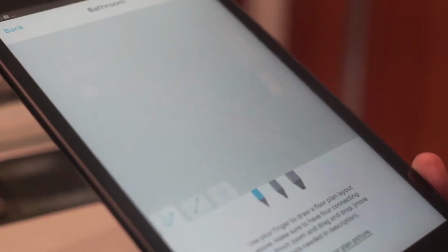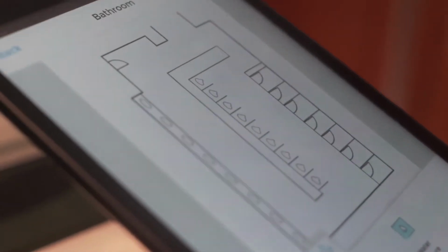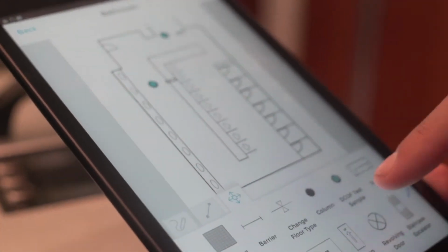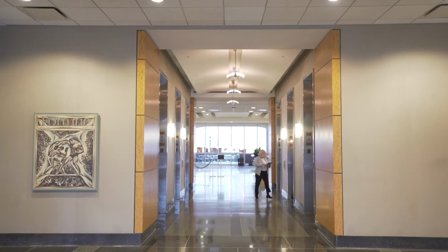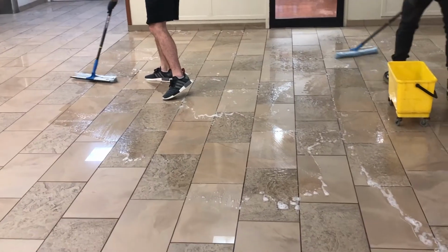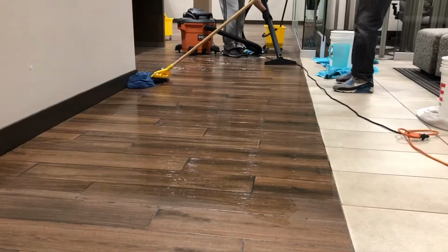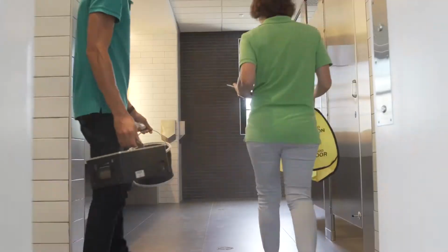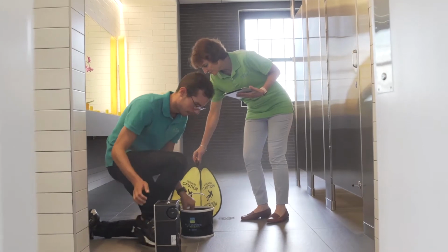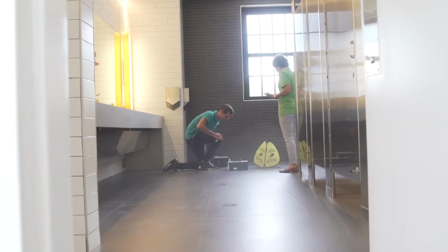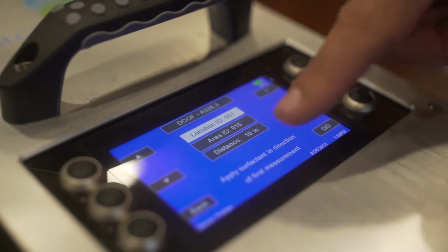Next, determine specific DCOF test locations within your test area based on the test objective. Note, test locations should include samples of both high and low traffic, materials of different sizes or textures, and materials commonly exposed to contaminants or other risks. Each test location must include 3 test samples. Keep in mind that the travel distance of your BOT-3000E should be set to 10 inches.